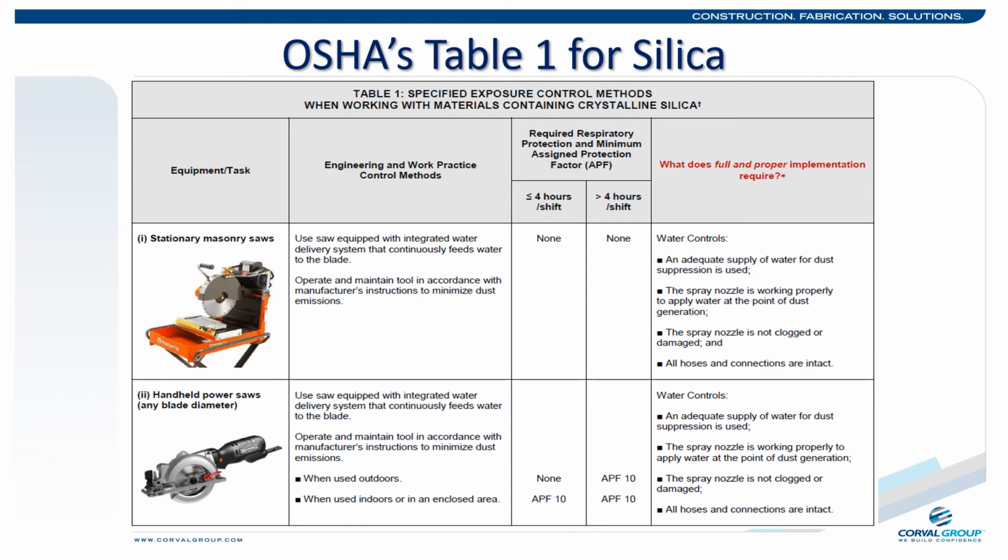The project's site-specific safety plan should include Table 1 and a plan around your tasks creating silica dust. Projects that do not have a site-specific safety plan shall reference Section 1A of the THA and contact safety prior to performing any activity that has the potential of creating silica dust.